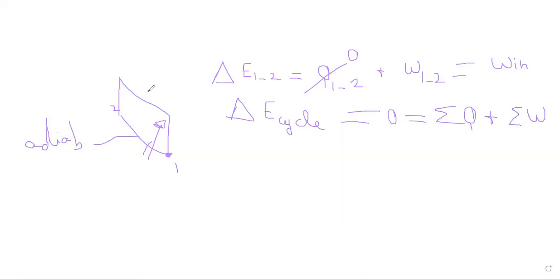Okay, so if I consider the whole cycle, I can say that Qin, which is the heat input during the combustion, minus Q out, which is the heat rejection during the cooling phase, related to the exhaust of gases in the real case, plus Win, which is the work we put in compression, minus W out, which is the work given by the system to the crankshaft, equals 0.